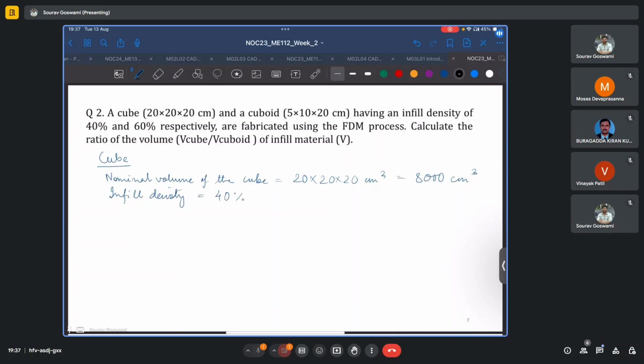Say in each layer, you deposit these two perimeters, outer and inner, and then you deposit it via some zigzag. Now, the step over, depending on the bead width, and depending on other process parameters, there might be some gaps here.